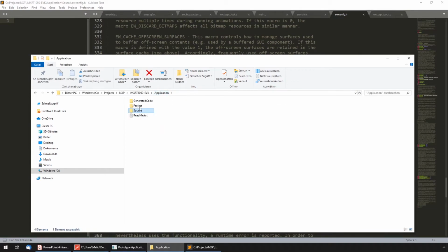Now going to the project itself, just to make it very brief. What we have is pre-configured projects for various toolchains. For the NXP environment, we have, of course, MCUXpresso, the own IDE tool of NXP. However, if you want to use IAR, then you can use EWARM. If you want to use Keil MDK with Microvision, then you can use MDK ARM, or a very simple one, GCC based, which is only a makefile with the proper rules and utilities set up and dedicated loaders, etc., that can be used with a command line build environment.